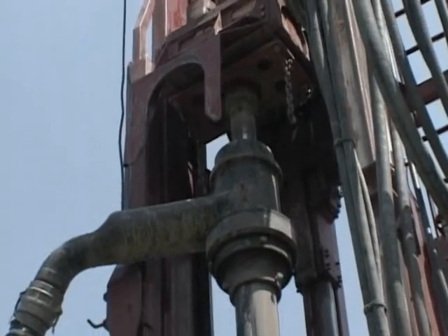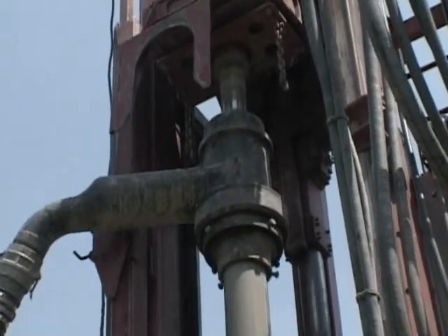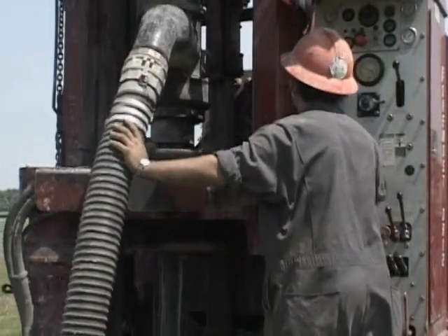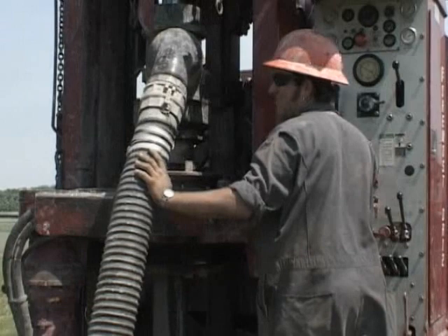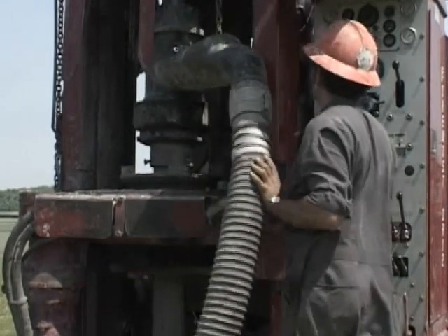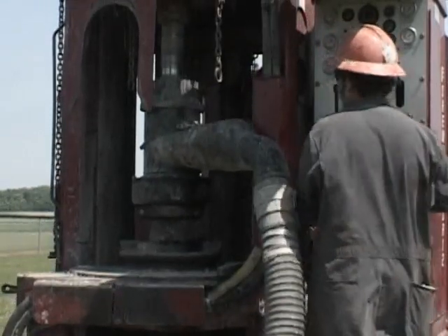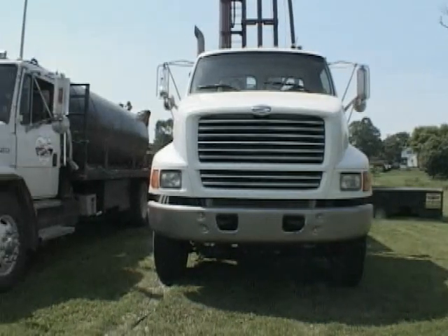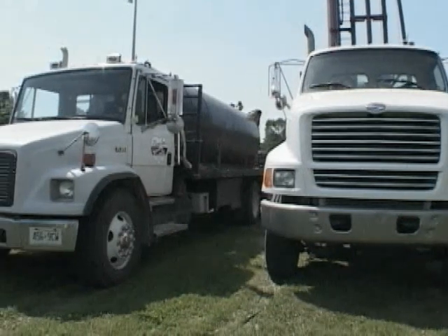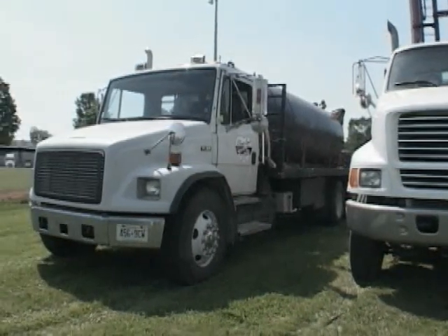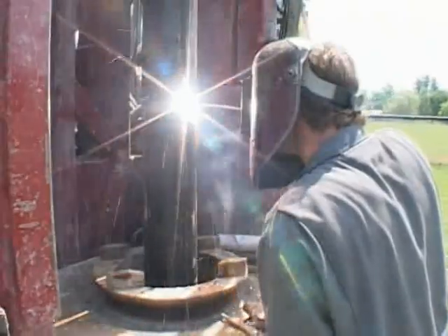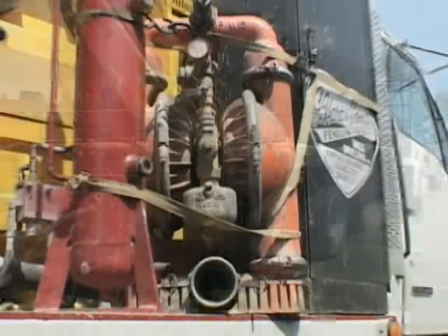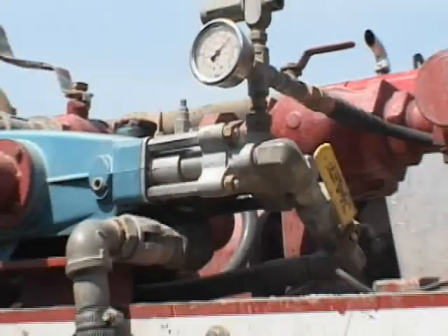These rigs can be expensive to operate and maintain. However, the dual rotary rig can drill through any formation, producing straight boreholes and excellent penetration rates. This system is also relatively easy to operate compared to some of the other drilling systems in use. The power for the drilling operation is provided by the truck engine itself. Separate support vehicles include a significant amount of water, as well as the usual welding and cutting equipment. Other support equipment includes a knuckle boom crane, grouting pump, and water injection pump.